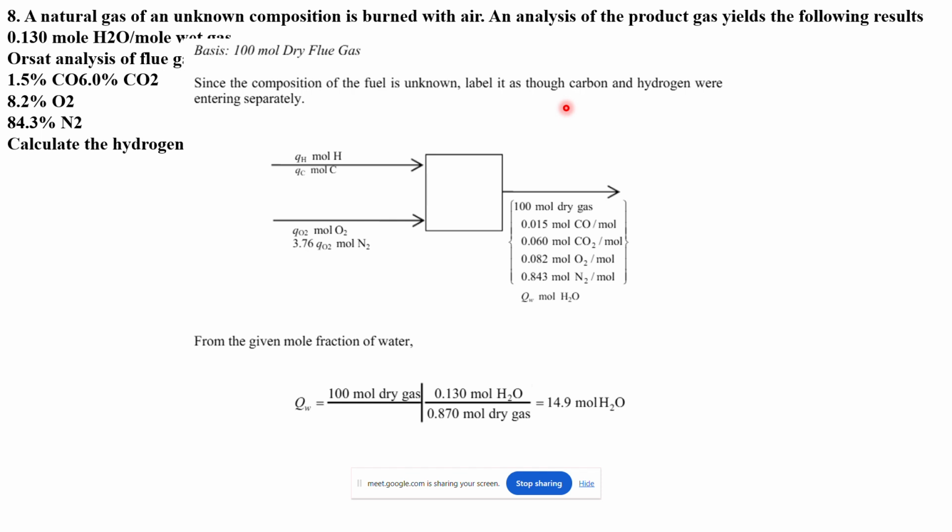Whatever moles of hydrogen and carbon go into the fuel source are going to get converted into CO, CO2 or H2O. We are also providing some air, because we can see around 84.3% N2. So we are clear that we have to provide some excess air, or stoichiometric air, for the proper burning of that natural gas. We don't know the molar quantity of the O2 and other things.